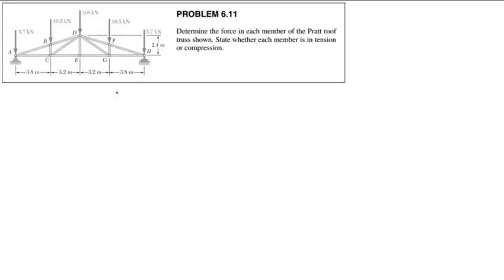Let us observe. I'm looking at this and something pops out at me. What pops out at me about this truss? It's symmetric. Yes, exactly. It is a symmetric truss. So therefore, we will be able to use arguments based on symmetry. So I can immediately determine the reactions without doing a balance of moments or anything like that.